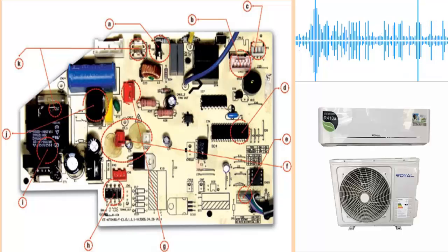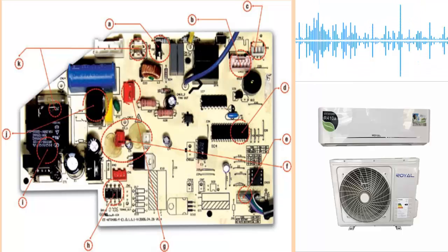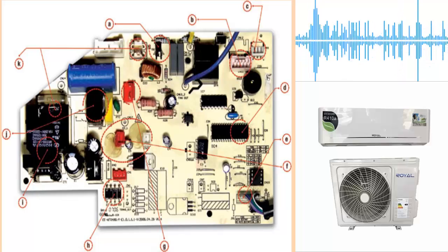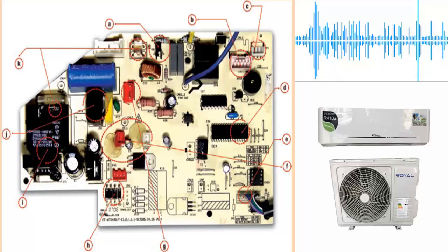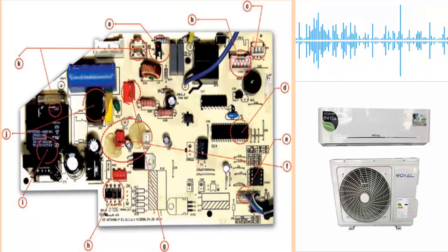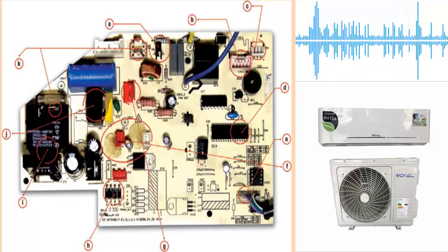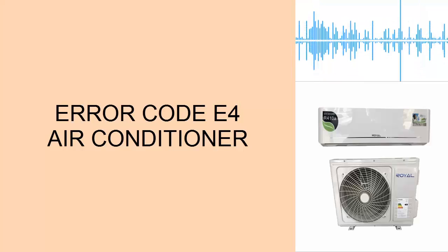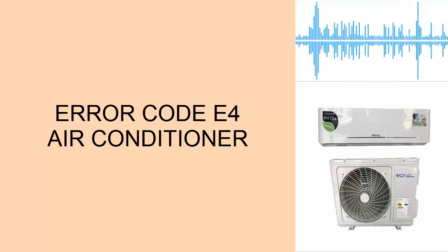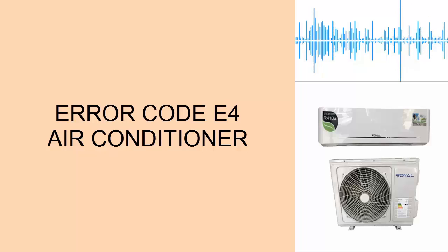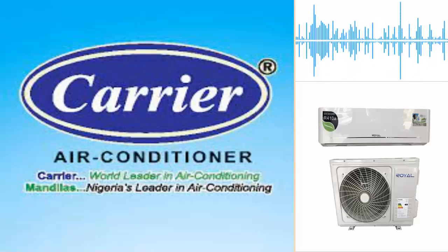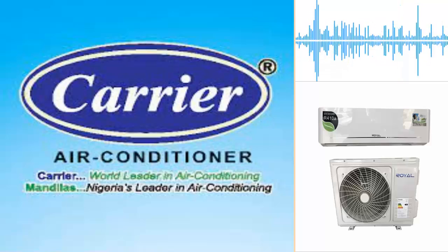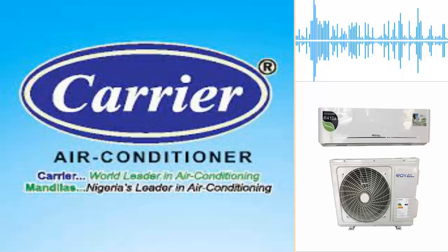The corresponding control board is responsible for regularly providing a voltage, whose value varies with resistance and, on average, is around 5 volts. The brands affected by this error are as follows. Carrier: issues with an open circuit or a short circuit in the ambient temperature sensor, either indoor or outdoor, depending on the unit's model.